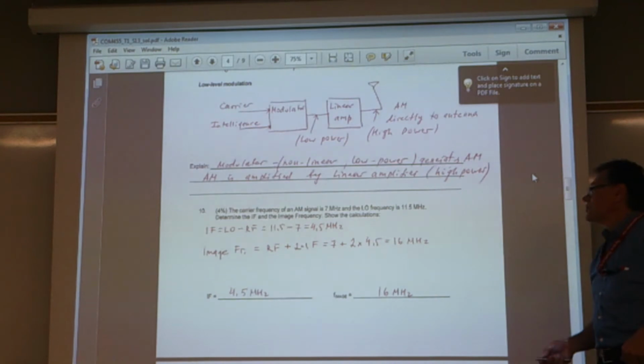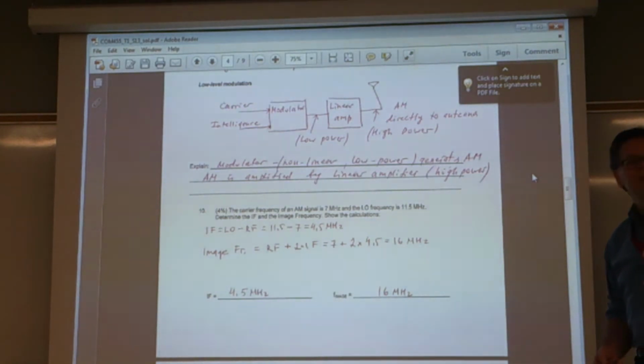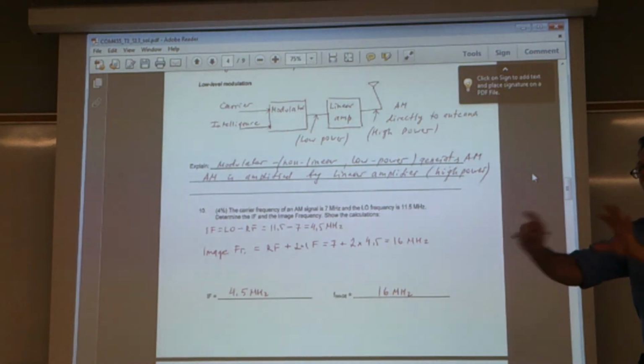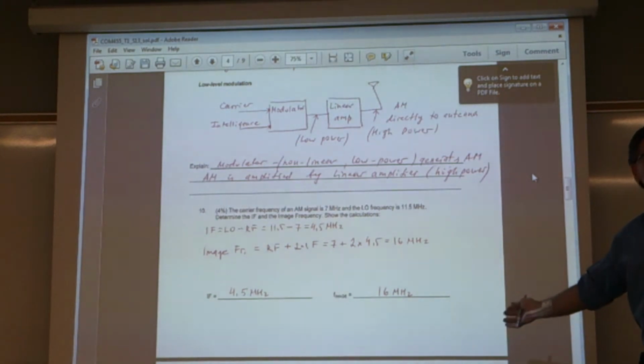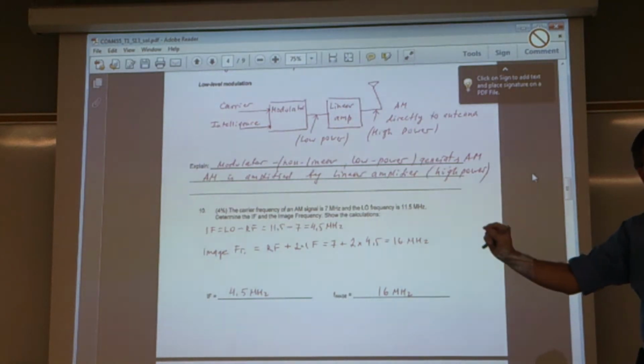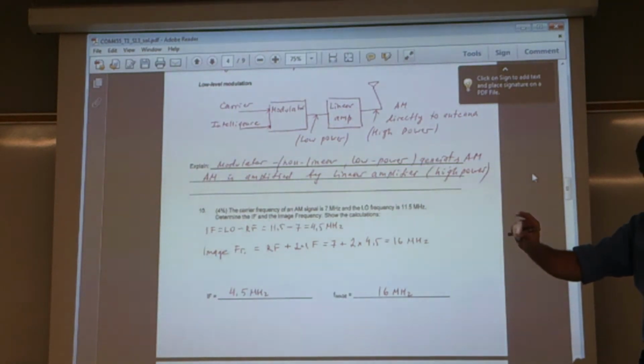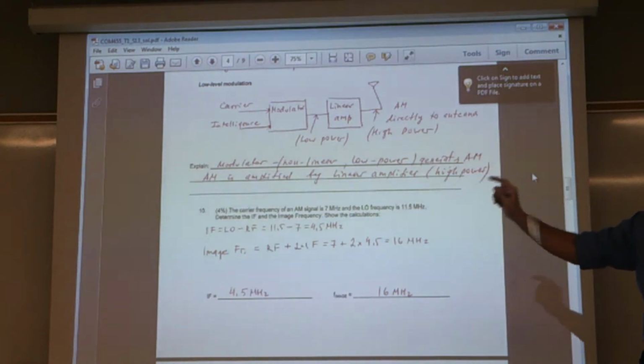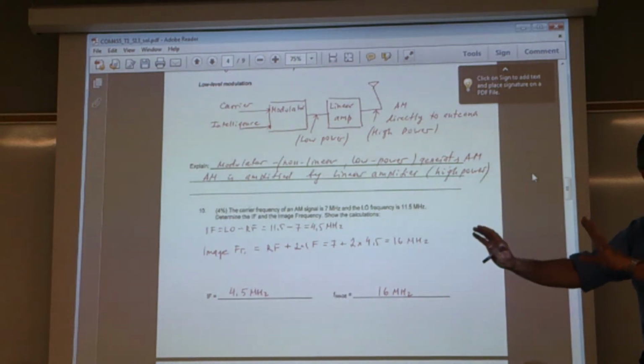Okay, next question. Someone was asking, what is IF? IF is an intermediate frequency. Everything we translate in the receiver to the IF. We have different carriers at the input, but when we translate all these different carriers to this one carrier, only one, everything works with this one frequency. Easy to design. We don't need to have huge bandwidth for all these channels. Just bandwidth for this 455 plus information manipulation. And all amplifiers, resonators, mixers, they all work with the same frequency. That's the only reason.